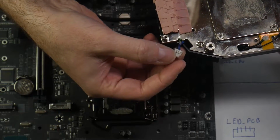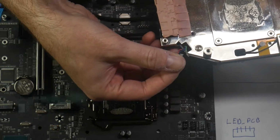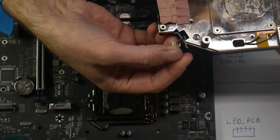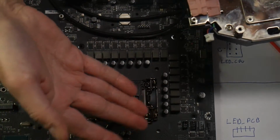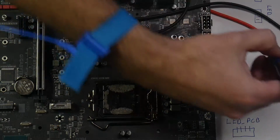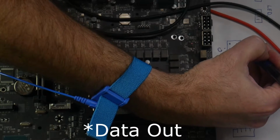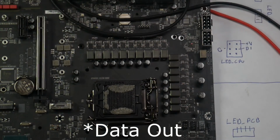So that leaves me with the red wire, which surprisingly is data in this case because there's 3 pins missing. We know what ground and voltage are, so therefore that 3rd pin right there is data in. So we'll put DI, data in. So we've mapped that out. Now that's how I was able to have it kind of glowing like that.